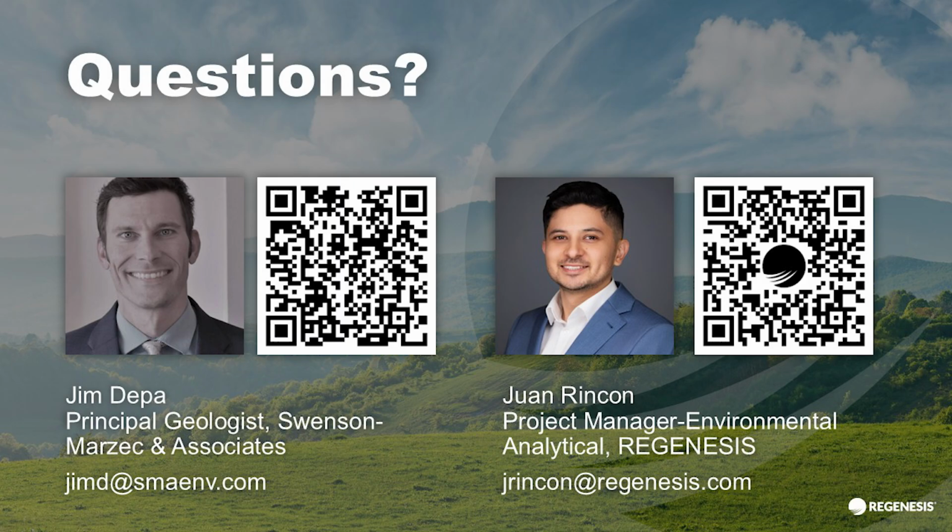Okay, thanks, Jim. So let's see, here's another question for Juan. How does MIHPT data correlate to flux tracer data? So we have seen data comparison in various sites. They correlate quite well. Of course, what we correlate the most is the Darcy velocity, once we have an effective porosity to the estimated hydraulic conductivity measured with HPT.